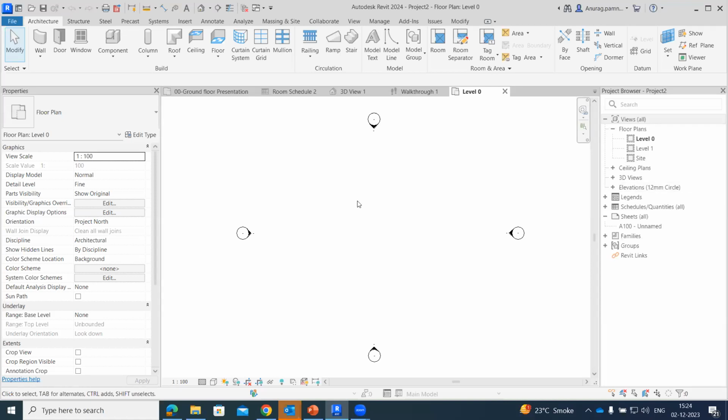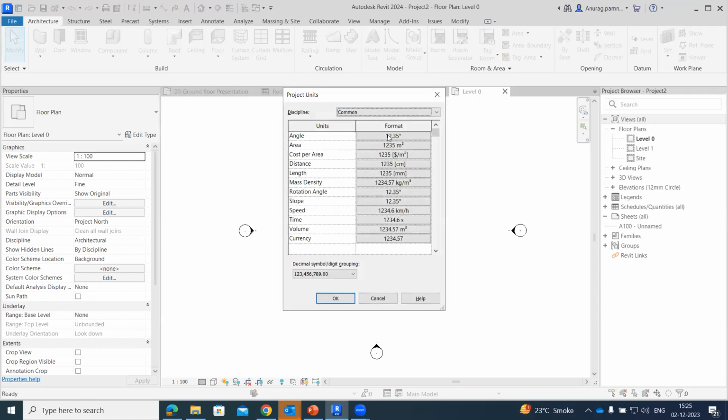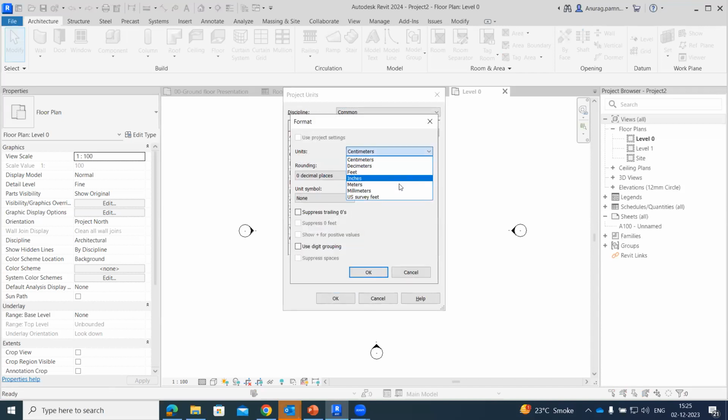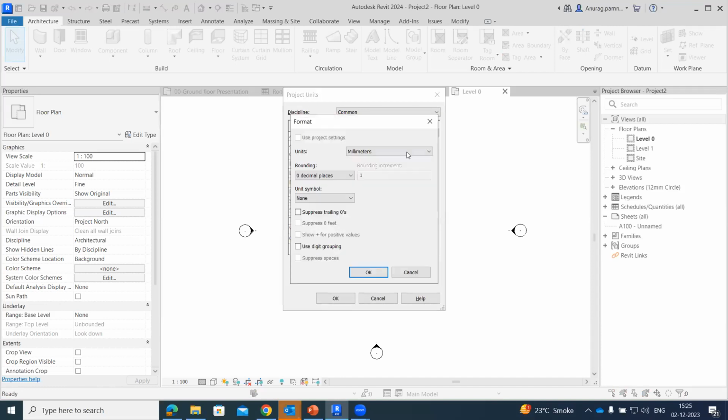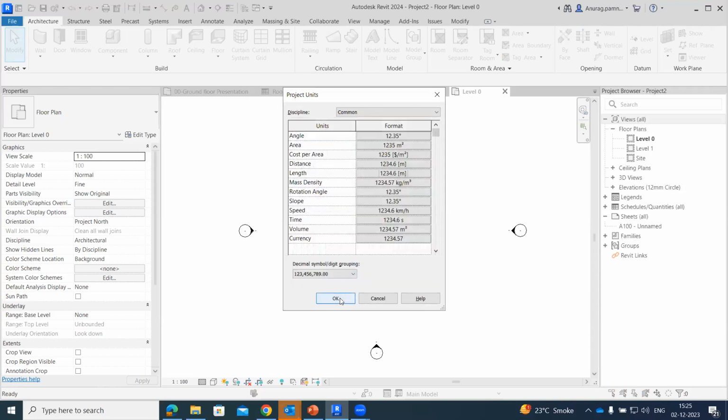So the first part of it is to set up the units, where I'm talking more about the design initiation phase and would be developing certain data out of it. So the first thing is to set up the units. I would be typing UN, and I can work on particular units. Say I'm working on standard metric units and I can set up to what decimal places I need the unit. Similarly with length, I can set this and associate it with particular decimal points and say okay.